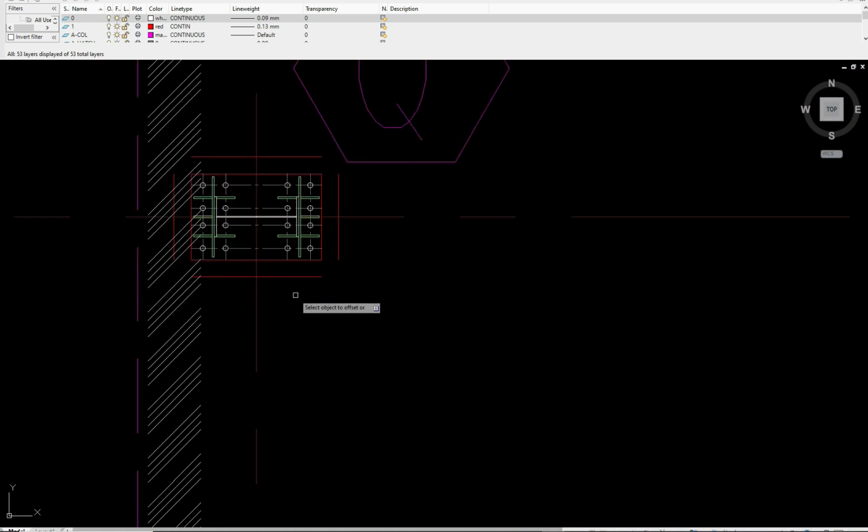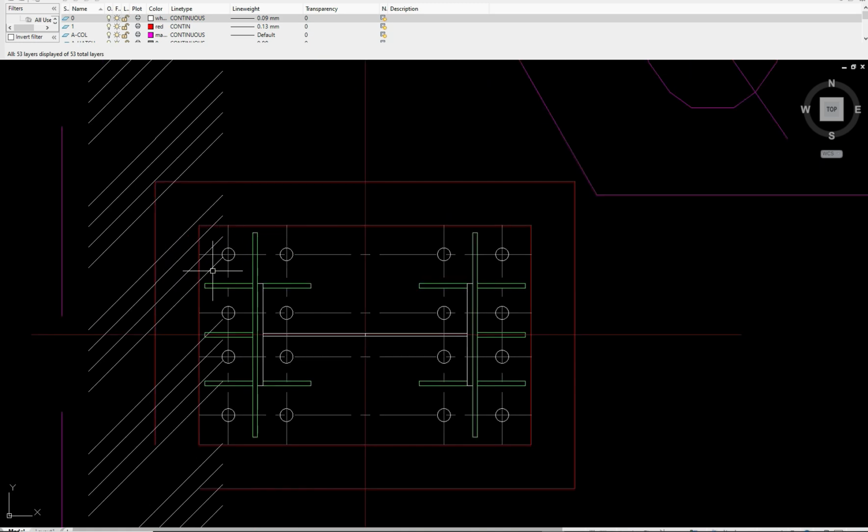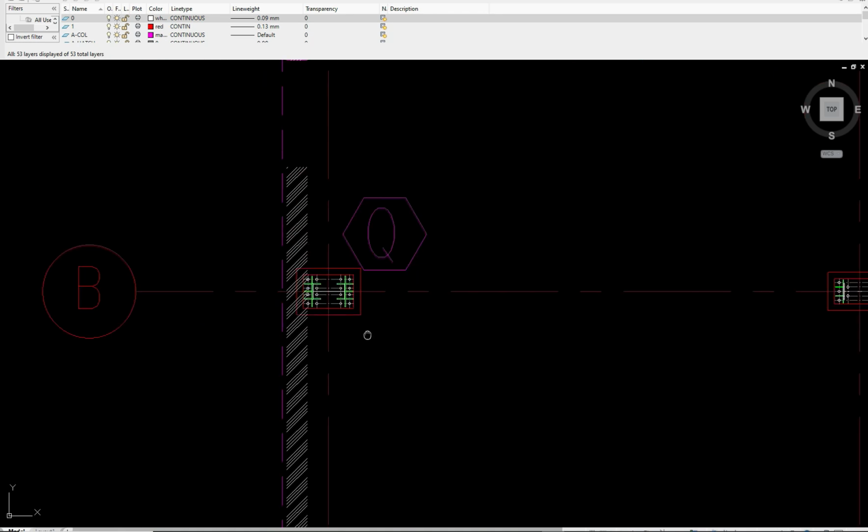Now this part, you see, the draftsman or detailer has actually made this base plate as lines, not a rectangle. So the outer offset lines are not joined, so we can use the fillet command to do it. F is the command, then type R, because at times R could be different, then type 0, then select the objects, so it is joined, then enter again, select objects, joined, joined, joined. So we have this base plate.